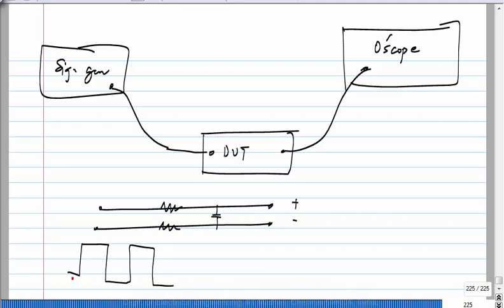Yeah, you may have calculated it, it will look like some rounded off stuff, and the exact details will depend on the values of R and C, the frequency of the square wave, and what is actually here and things like that. But this is where giving sinusoids is valuable. If you have a sinusoid here or here, you will have the sinusoid with the same frequency. Its amplitude may be different, that is fine. Here you apply 1 volt and here you may only get 0.8 volts or something. But it will still be a sinusoid.